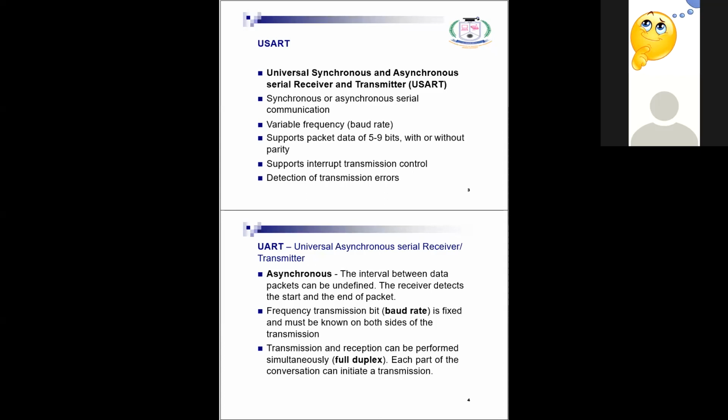If it doesn't match, automatically a parity error will come into the picture. If we don't identify the start bit or stop bit, automatically a framing error will come. So to detect errors while transmitting and receiving, we always look at the start bit, stop bit, and in between the data bits.